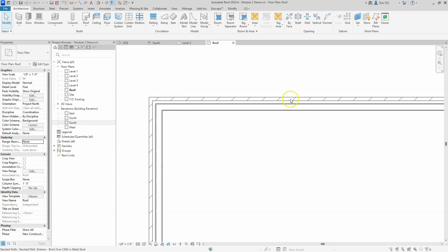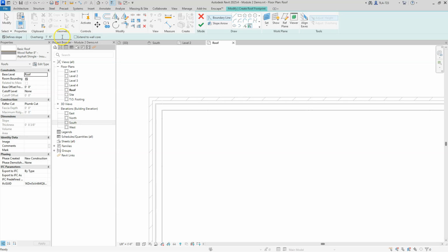All right, so I've had sort of mixed results with how Revit behaves, and honestly I haven't completely figured out exactly why there's such a variation in how it behaves and the different options that are available, but we're just going to roll with it, and we'll take what Revit gives us because there's always a workaround with it. Here's what I mean. Let's go back to the roof tool. We're going to again use roof by footprint, and then make sure you remove the overhang, set that to 0, and uncheck define slope. Again, we're creating a flat roof on this thing. Sort of. All right, and we'll talk about that in a minute.